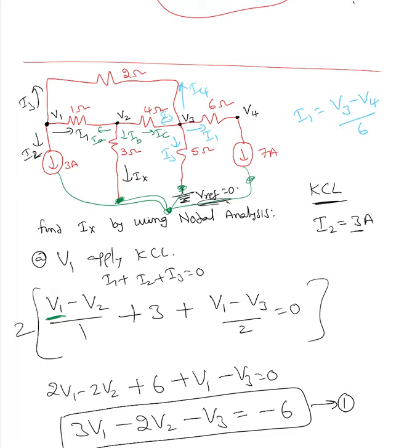That will increase my number of equations. Instead of that, can I write, since this I1 is not splitting anywhere, the current passing through this is also I1? Can I take directly I1 equal to 7 ampere? Okay, I can choose I1 equal to 7 ampere instead of doing this.